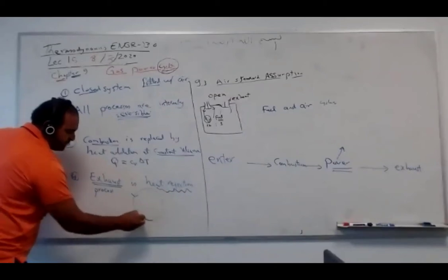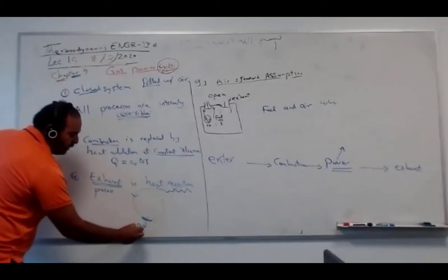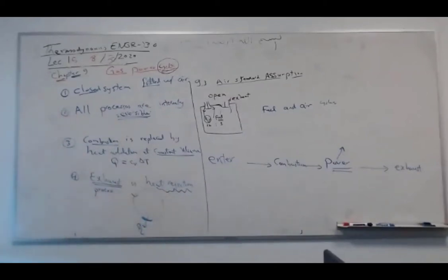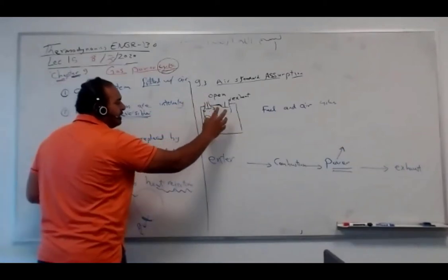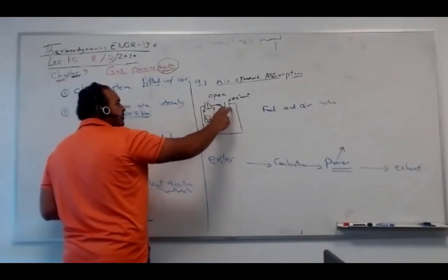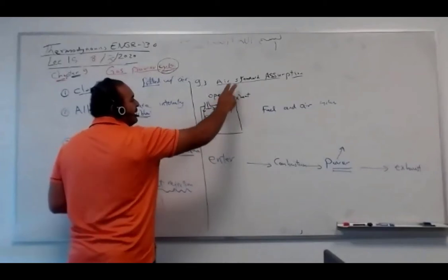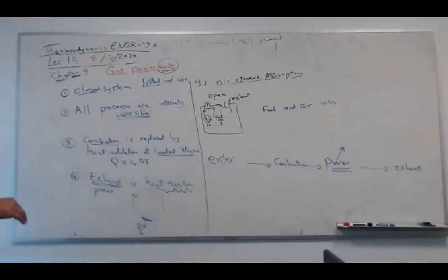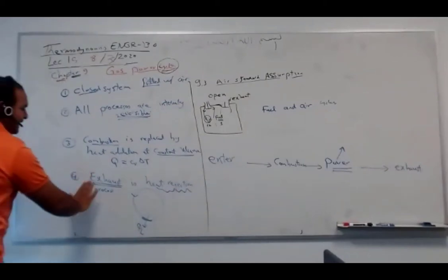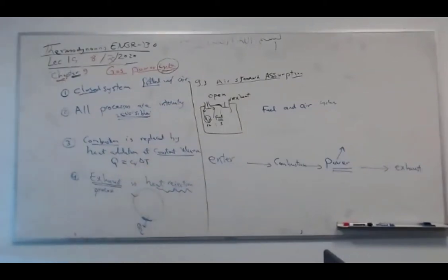Part of it is heat rejection, which we assume is Q low, something we reject some heat. And that's it. We continue the cycle, which is not really a cycle. Actually, we input new fluid and we burn it and let the gases go away and enter new ones. But this is hard to treat now. So for simplicity, I assume just heat rejection. We just dump some heat outside, which is Q low.